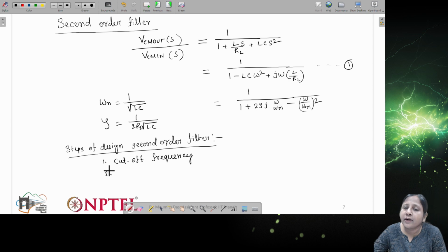That we can find only by plotting the noise or measuring the noise from the evaluation board. As I told you before, we have to measure the noise. Once we have the noise information, we can compare it with the standard given. From the standard we can see where exactly the attenuation is required, and at what frequency level.